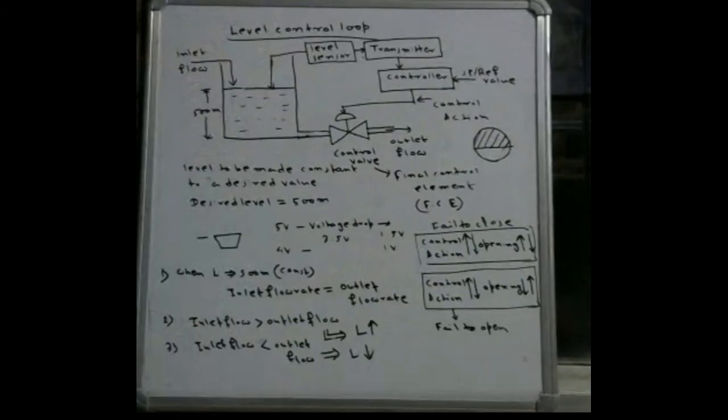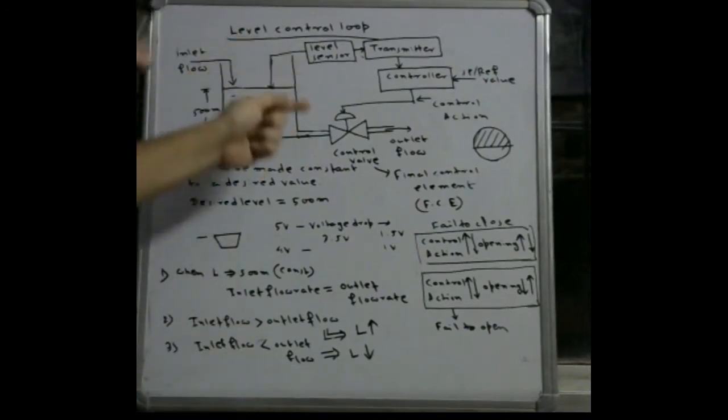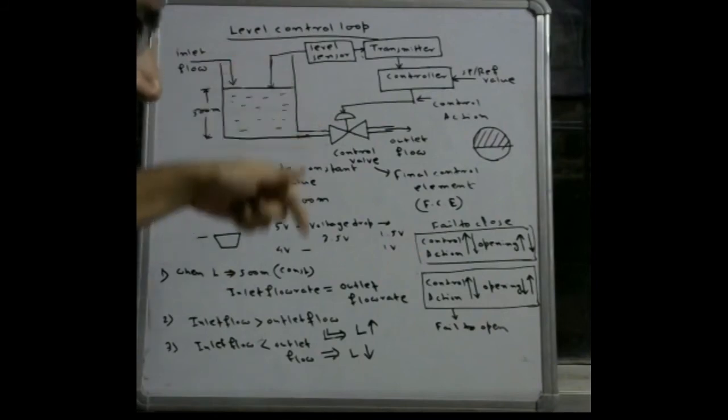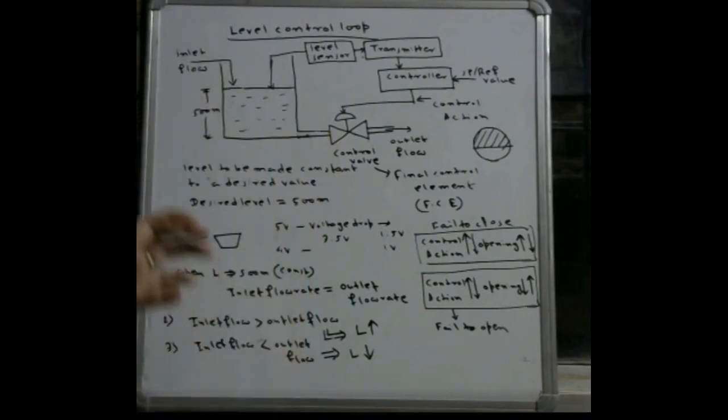This is done by an electrical motor. So this motor will convert the electrical energy to the mechanical form, and this one is in the form of a linear displacement of the plug. So this electrical motor, which is inbuilt inside the control valve, acts as an actuator.